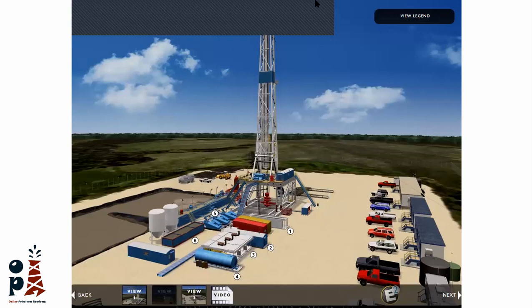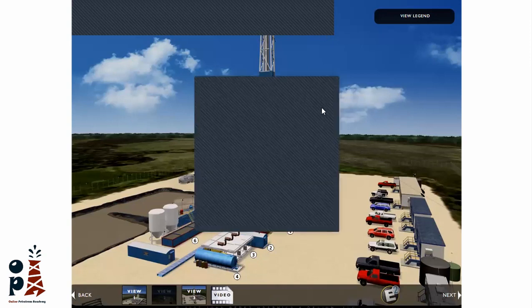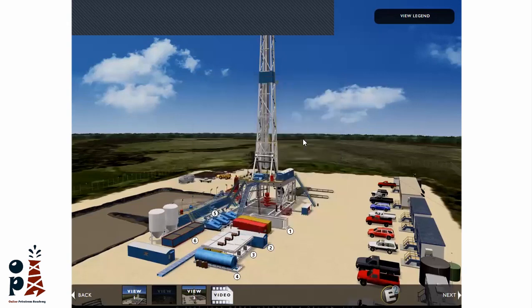So what else, guys? Okay, I see a lot of messages about H2S, and the guys are replying to each other. It's good that we help each other to deliver the message. Okay, Jeffy is saying that the first barrier is the drilling fluid. This is the first barrier already, and in case there is any failure of this first barrier, we use the secondary barrier, which is the BOP.